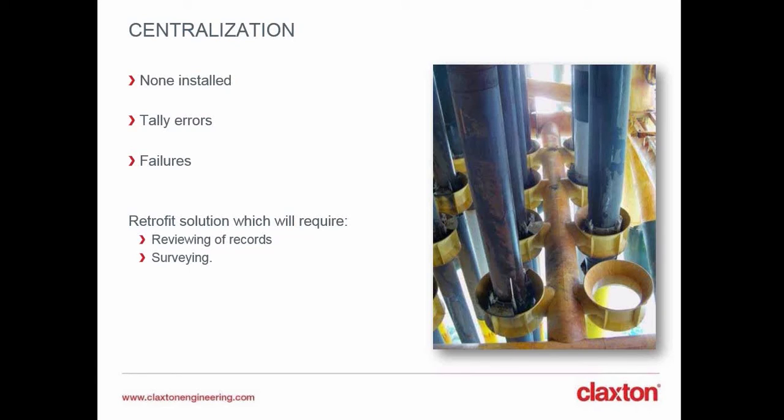For all these cases, again, reviewing the records will be a key thing to do. Information recorded during the installation or during inspections could really help make sure that if mistakes were made, they're not repeated to start with. For most cases, a survey will be required because although sometimes you do have the drawings available for the platform and the conductor, the conditions might have changed quite a lot. For subsea applications, you might have a considerable amount of marine growth, or things might have changed and you're not aware.